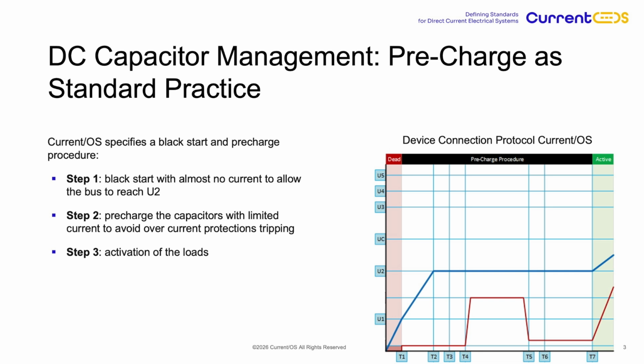In the case of specialized LV-DC systems, for example data centers or dedicated industrial process islands, other approaches exist. For example, a single centralized pre-charger may be used for an entire circuit. However, this approach requires every device connected to that circuit to be fully known and carefully coordinated. Future modifications or expansions are therefore very limited.